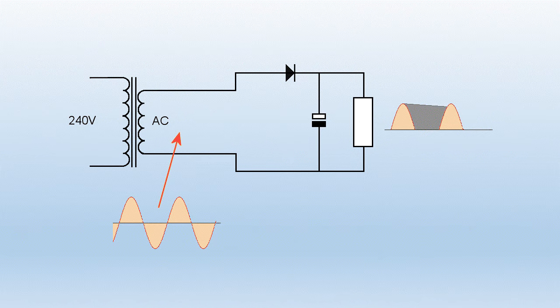We can normally put a capacitor across the load so it gets charged in between each of the half wave pulses. The grey area you see is as the voltage slowly drops as current is taken out of the reservoir capacitor and then replenished when the next half cycle arrives.